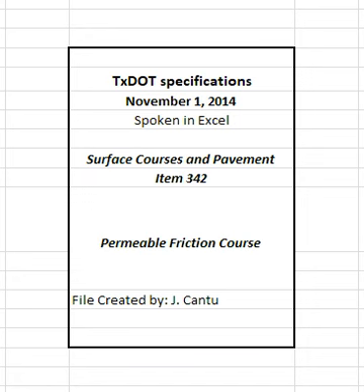Use the procedures described in Tex-233-F to plot the results of all production and placement testing, when directed. Update the control charts as soon as test results for each sublot become available. Make the control charts readily accessible at the field laboratory. The engineer may suspend production for failure to update control charts.